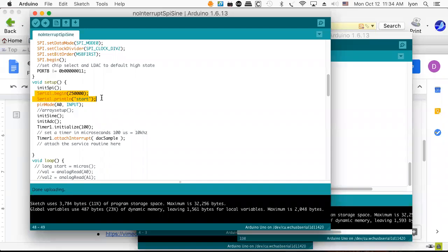Now, outputting to the serial port, it says it's fast, right? 250, whatever this is, kilobits, kilobaud. But the problem is that's still really, really slow compared with a 16 megahertz computer. And in fact, if you think about it, I could probably change this to something really slow, like 9600 baud. And then upload it again, I suppose. And it should still run properly in theory, I hope.